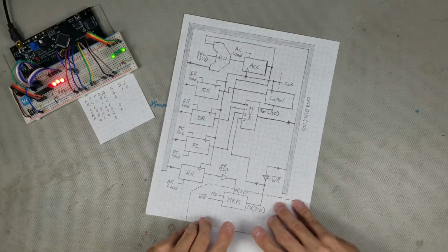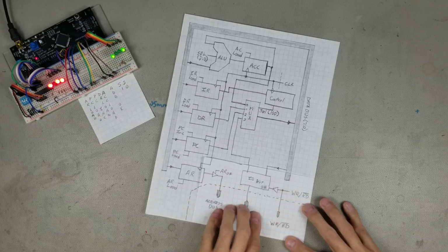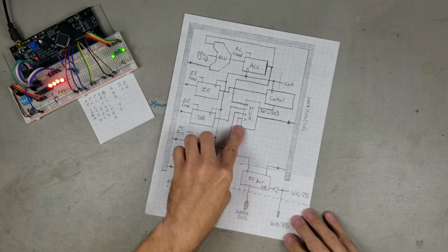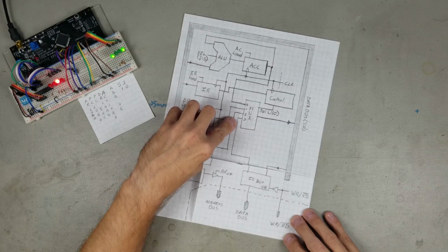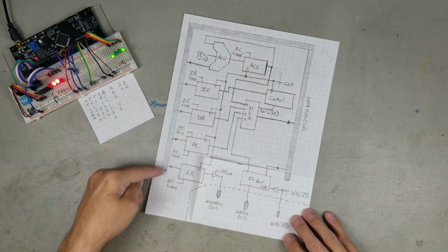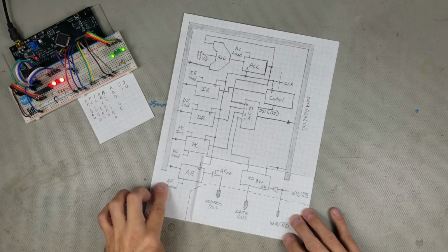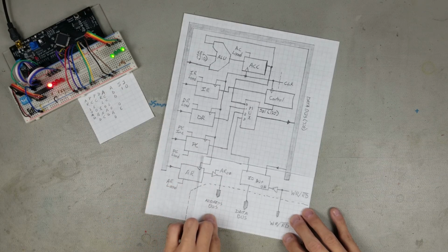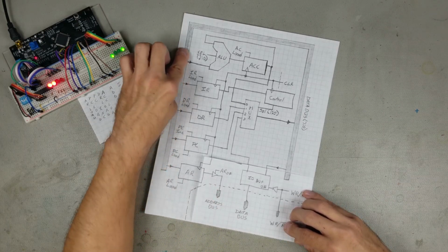Using the outline and redrawing the output section with the I/O buffer, you can see how the data will move around. Setting the read-write line to low, it takes data from the data bus and funnels it to the MUX, input number 3. If we set the select lines to 11, then that data is sent to the internal data bus and is accessible by all the registers. Then by setting the AR load high and cycling the clock, the value on the internal data bus is loaded into the address register, which is then sent out to the address bus. In this way, it's possible to load more than one register simply by setting the appropriate load pins.